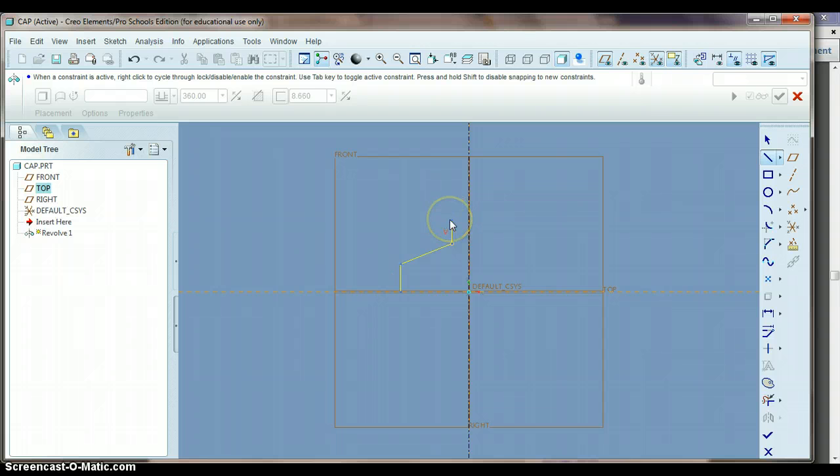One thing you want to watch out for is that you can make the top and bottom vertical lines the same. See how there's a red L by my top and on the bottom vertical line, you'll see them pop up in just a second. There they are. We don't want these to be the same, as that's indicating that they're the same length. So either go a little shorter or a little taller than that, left click, and then middle mouse wheel to finish that out.